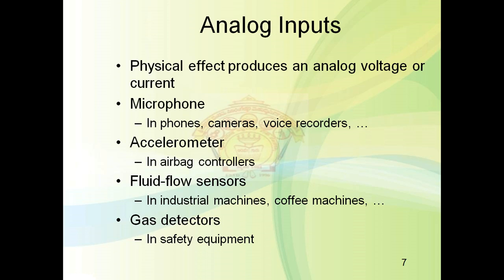One resistor is placed into the fluid stream, which cools it by an amount of temperature. Since the resistance depends on the temperature, the difference in resistance between the two resistors measures the flow rate. The resistance difference is detected to drive the analog input signal, and in this way we can detect the flow or rate of flow.